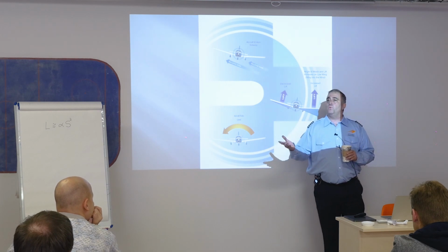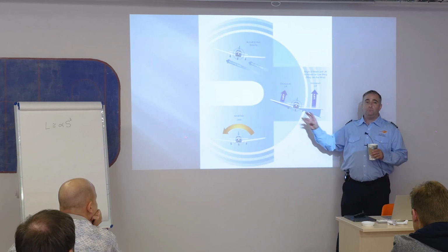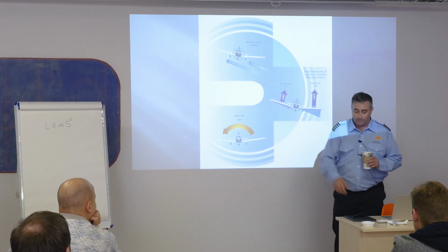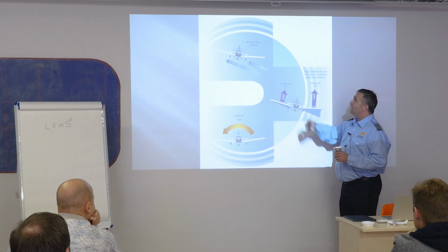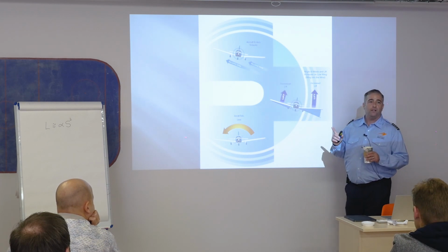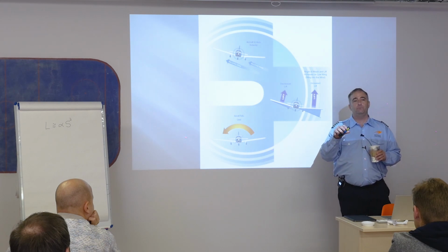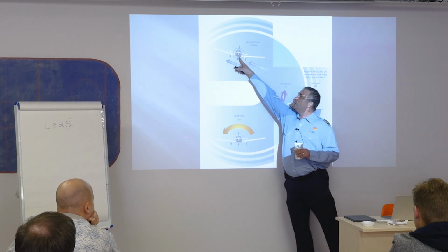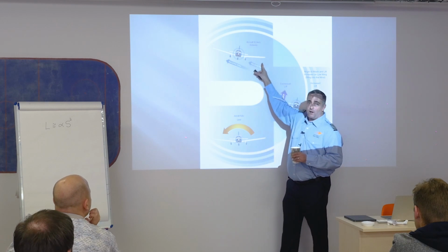The way that airplane wings are formed and the way the airplane wings are created, I'll have some relatively good controllability features that will allow me to fly this airplane well. Relative wind here, as the aircraft enters a side slip, it will allow that one wing in a low bank condition to create more lift because of the dihedral, which is just the angle that's formed straight from the horizon to that wing.